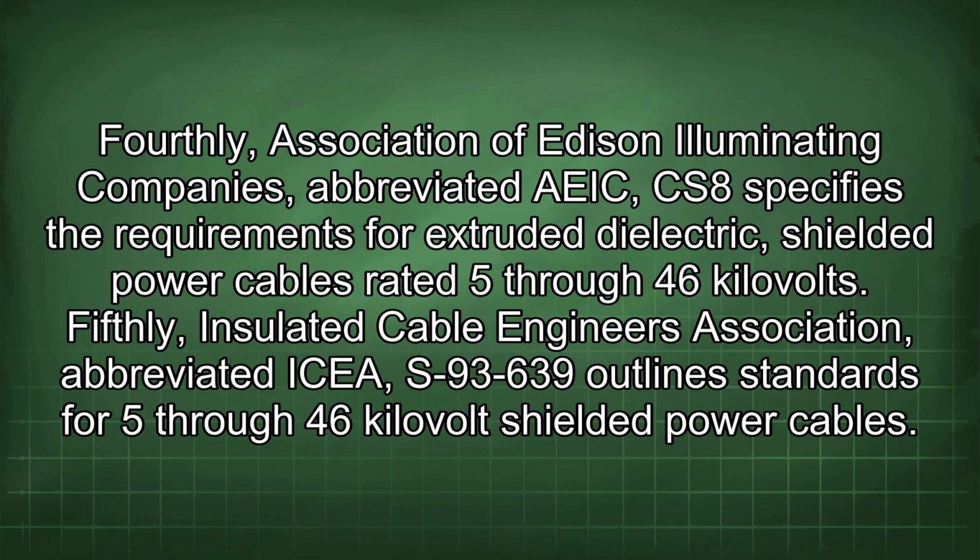Fourthly, Association of Edison Illuminating Companies, abbreviated AEIC, CS8 specifies the requirements for extruded dielectric shielded power cables rated 5 through 46 kV. Fifthly, Insulated Cable Engineers Association, abbreviated ICEA, S-93-639 outlines standards for 5 through 46 kV shielded power cables.